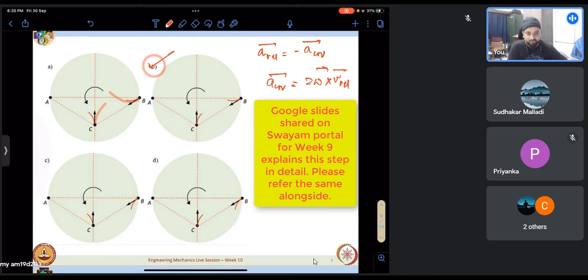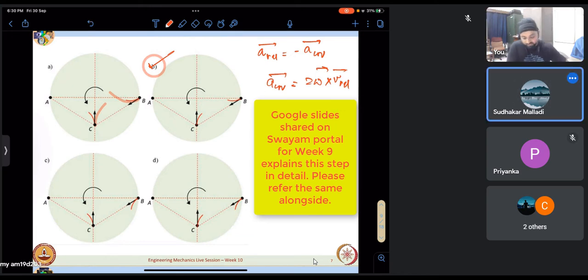Okay, so I take it that this is clear. The omega is pointing out of the plane of our screen. VREL is this way. Omega cross VREL, our Coriolis acceleration, is that way. What we will observe while rotating would be opposite of this, so it will be towards the right.